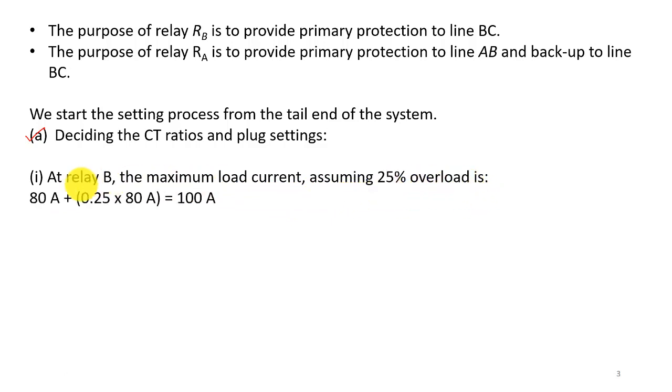The 80 ampere is actually the rated load current, not the maximum. Adding another 25% makes the maximum load current 100 ampere.